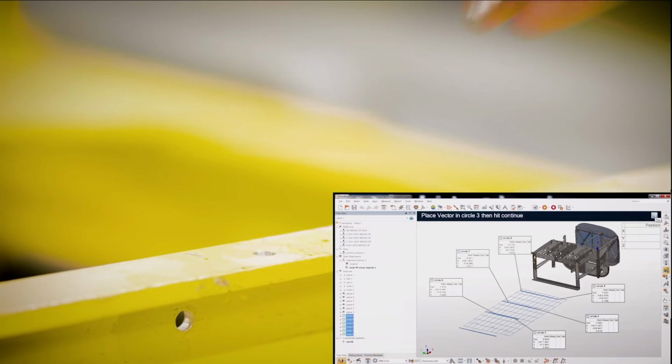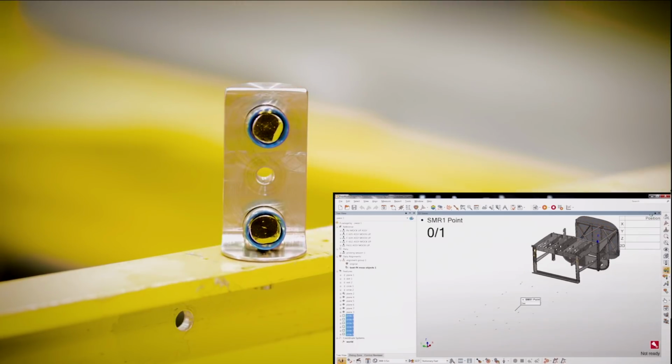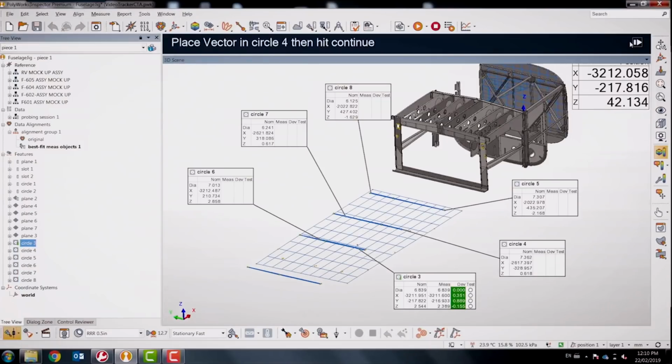Once inserted into the hole, the vector bar and reflectors are stable, so the measurement script can drive the beam to the reflectors. The macro script sets the feature diameter based on the vector bar parameters and calculates the orientation and position from the reflector readings.